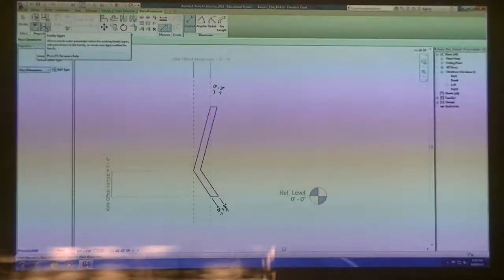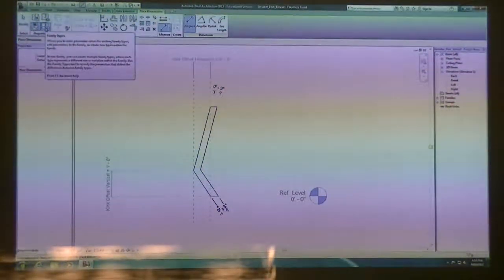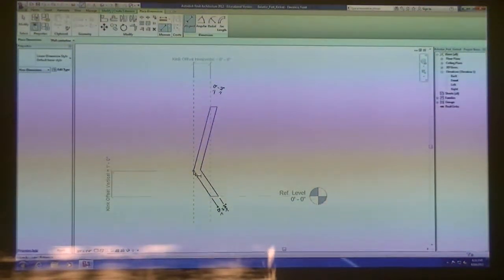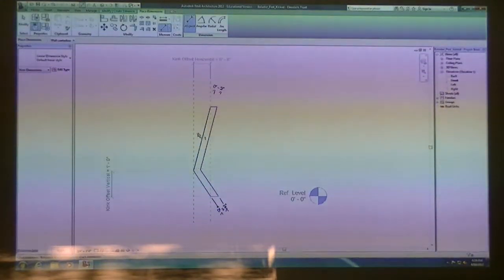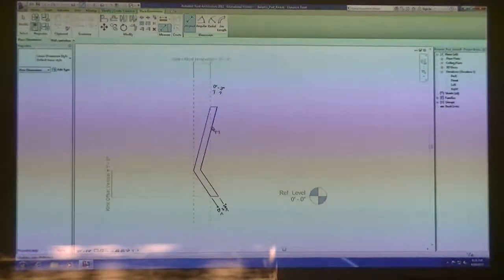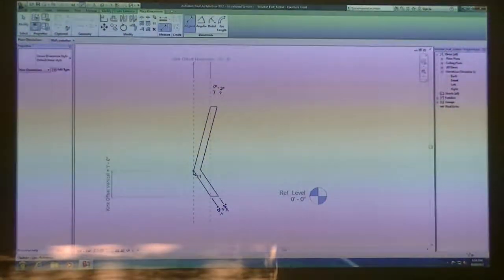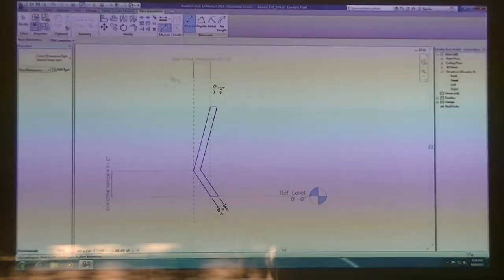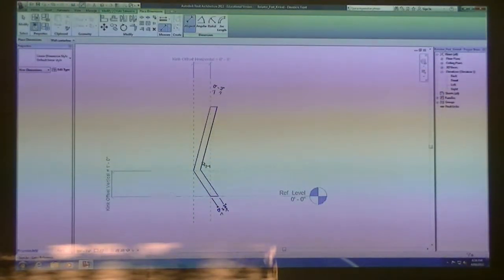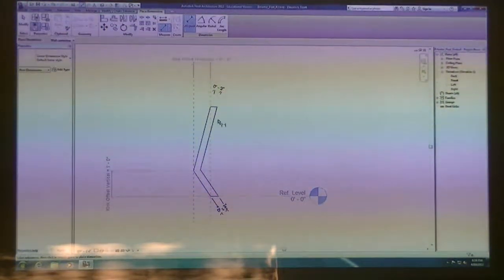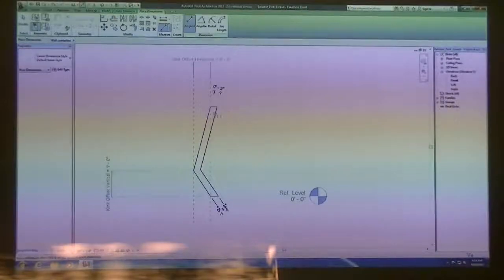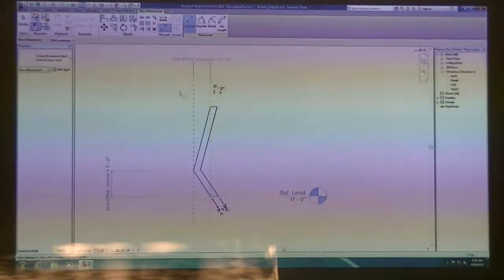Right now we did a 3-inch and a 3-inch. Later on I might want to change that if I decide that it looks too bulky. And I also want it to always be that dimension no matter how far this ends up kinking out or moving up. If we don't lock this dimension or give it a parameter, then if you move this reference line and change the kink offsets, let's say it moves further out, these lines will not know where to move to. They'll start to stretch, but they won't be parallel anymore. So I'm basically forcing a constraint to always keep this a 3-inch offset.